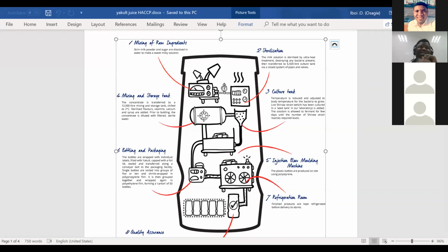You understand? I wish there was a marker board so you could see me demonstrating all this. So step 1 will be that. We've done with the flow chart, so the next thing is the hazard analysis. We need to identify the potential hazards that can happen in each of these steps that you have identified in your flow chart.